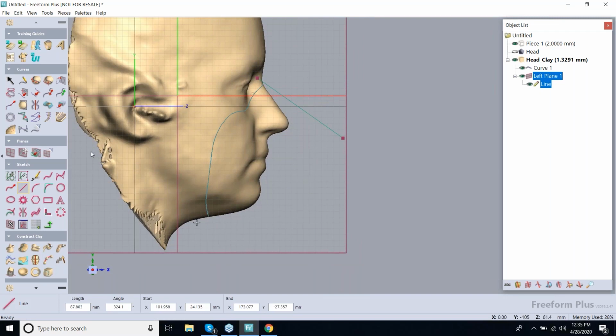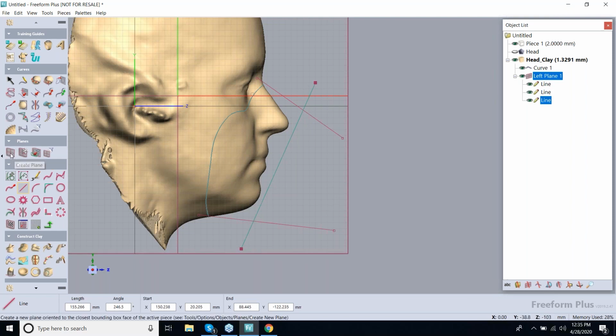This is going to be the profile of my mask. So again, I'm drawing another line at the chin, and I want to leave enough room so that this person can talk and move their chin freely without having any issues. There we go. Then I'll add a fillet to this sketch. Down here in the Dynabar, I can change it to a specific size. And I'll change that to 20,